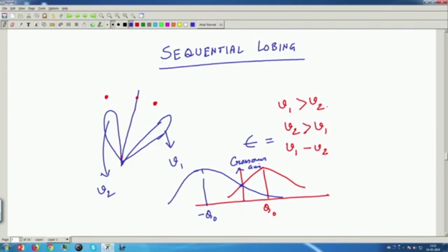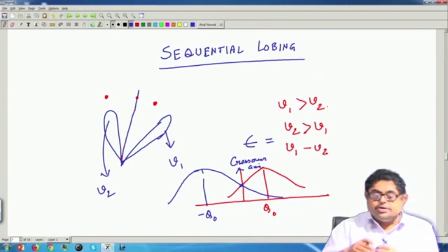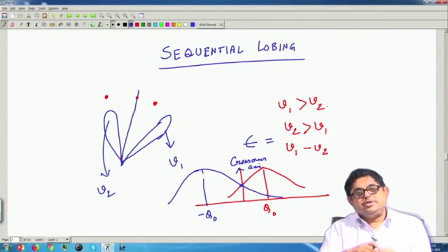Basically, it is a cluster of 4 feed horns illuminating a single antenna, arranged so that the right, left, up, down sectors are covered by successive antenna positions, with both transmission and reception at each position. The beams are switched sequentially, hence it is called sequential lobing. This is one form of tracking radar. By sequential lobing, we can find out the azimuth and elevation of the target.